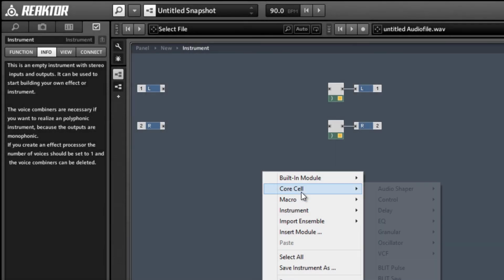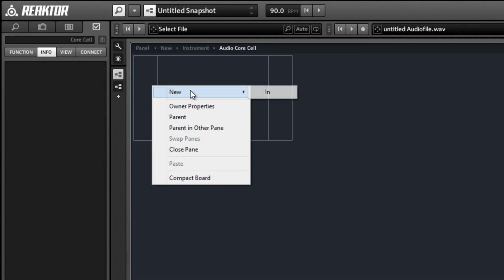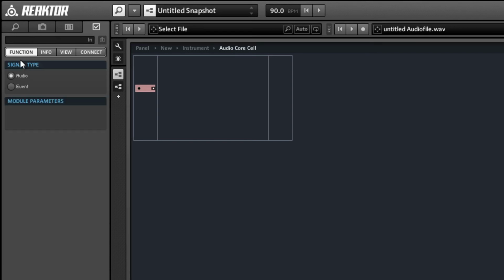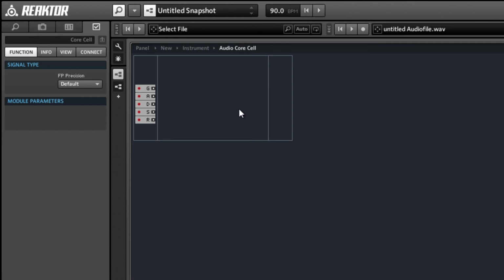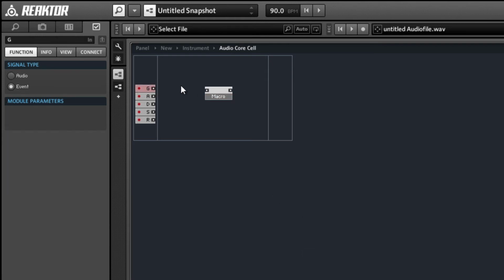In this video, I'll show you how to make a basic ADSR envelope in Core. And this project will tie together several of the things that we've been working on so far. We'll be using a counter to time how long the envelope has been either on or off for. We're going to use optional clocking, so we'll get a closer look at that, see how it works, and we'll be building a somewhat sophisticated router in order to control our optional clock signal.